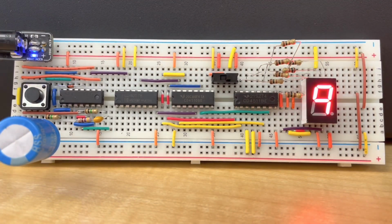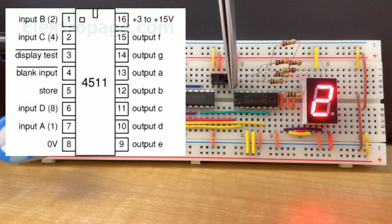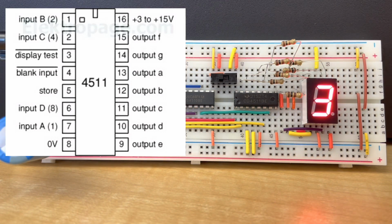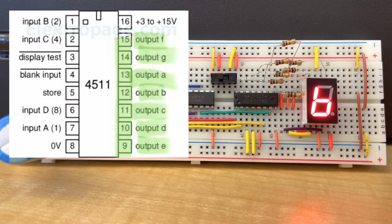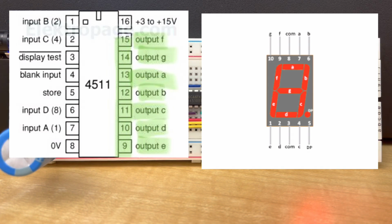The 7-segment display is a counter that can count from numbers 0 to 9. Every circuit that we have used was leading up to this. The 4511 pin configurations are also quite different compared to others. As you can see here, these are the pin configurations for the 4511. The 7 outputs on the 4511 connect quite easily to the 7-segment display as each of the outputs goes into its corresponding pin with one common ground.